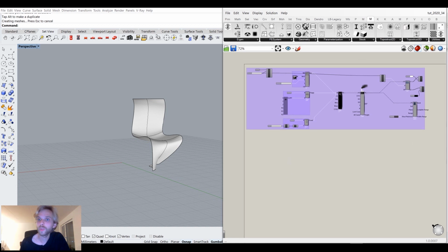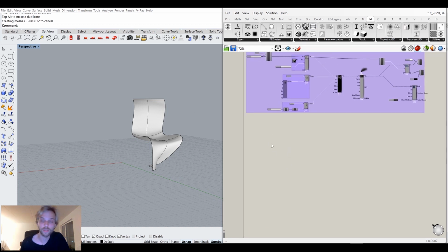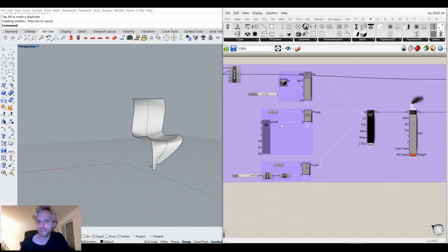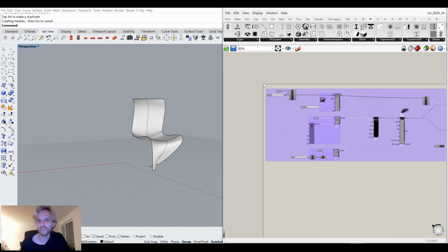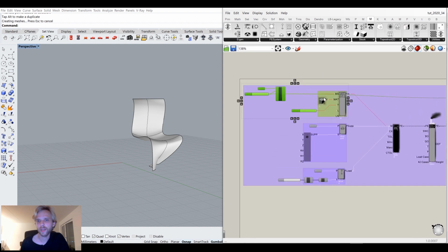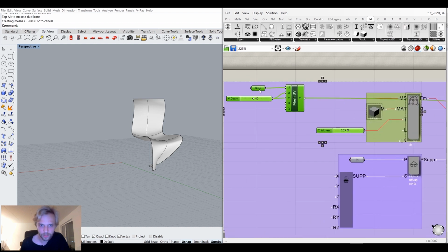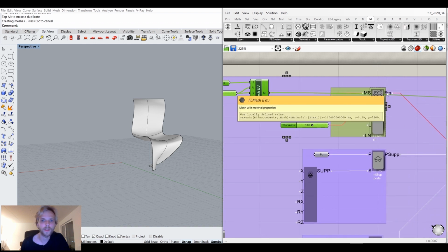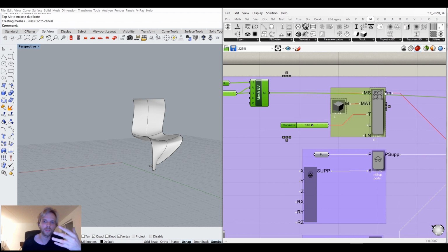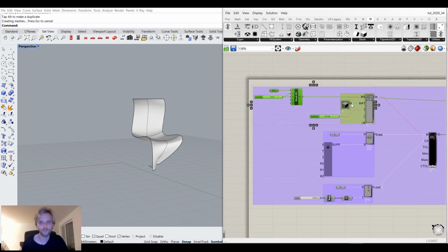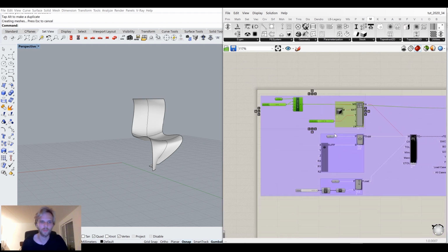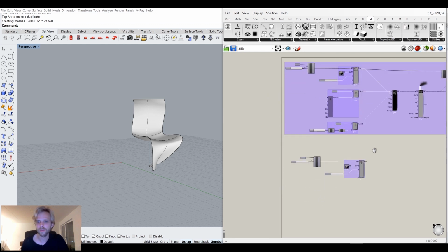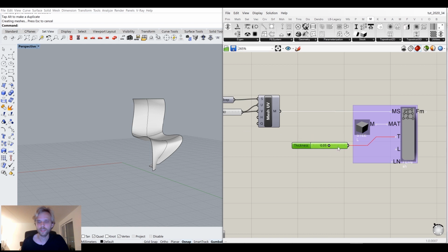So now we will bring it into Grasshopper. And I might reuse some of these parts. Yeah, I might as well. So let me grab the first part where we have the B-rep. We create a mesh from it, and we construct the FE mesh, the finite element mesh frame from it with steel and some thickness attached to it. Let us do that. Just like so.